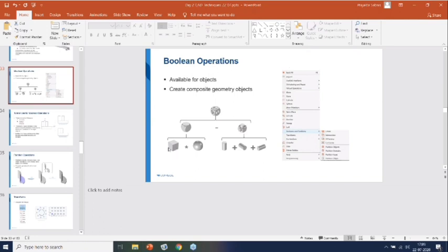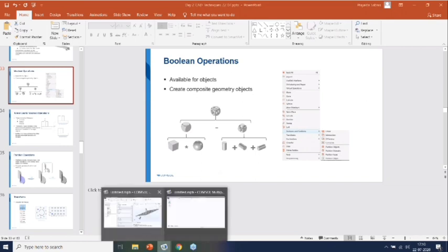So how you are adding these basic primitives may not matter, you can add first one block, one sphere, or first add 3 cylinders and then one block. But before performing the intersection operation, if you directly start performing an operation like subtracting one cylinder from this cube and then have an intersection operation with that resultant object, you may end up having a different resultant object altogether. So yes, the sequence will be important.